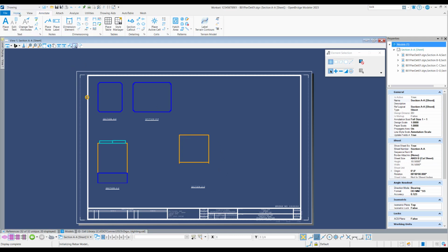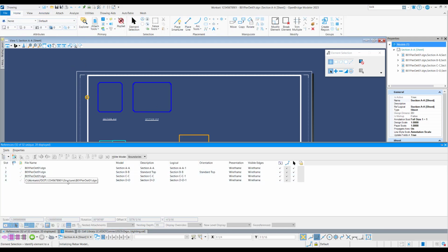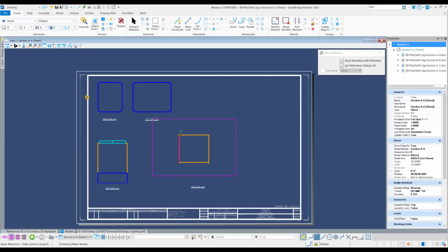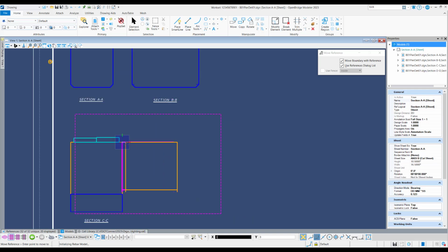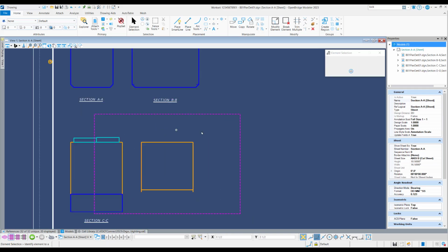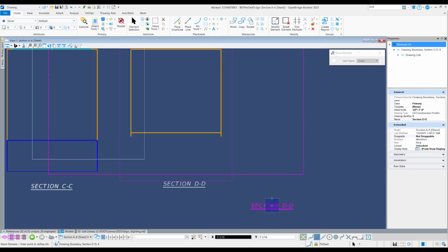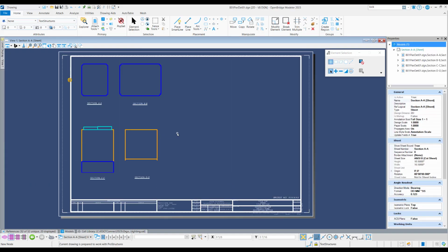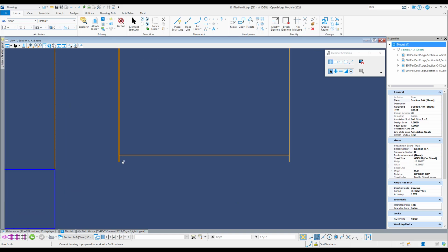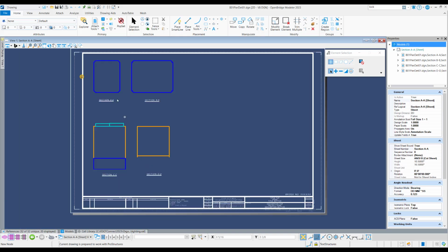So again, we'll go through the process of moving over the reference, section DD, click Move, line up the top, move it over a little bit, and then we'll grab that text and move it as well. All right, this looks good, but we are going to go ahead now and adjust the depth so that we no longer see these kind of like depth lines here.